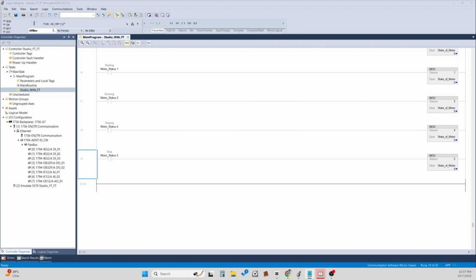About how to use the ramp button in FactoryTalk View Studio, and how you can link a tag with Studio 5000 Logix Designer in integer and either word and double. How you can simulate a tag and how you can increase or decrease any integer, either double integer, either long integer value.